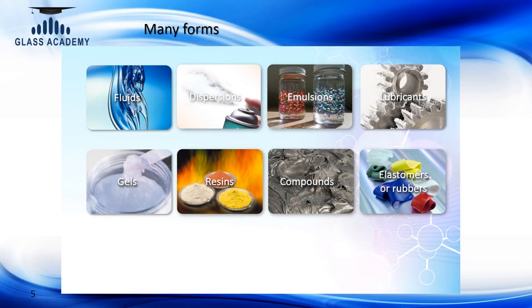So this final polymer which comes out can be converted into different forms. Okay, this can be formed like a fluid, this can act like a dispersion, like an aerosol, or it could be an emulsion with a water based system, or it can also be made into a grease type of compound like a lubricant, and by doing cross-linking polymerization you can make it into a gel, or you can convert it into a resin, compound, or elastomers or rubber. So the essential form of the sealants which are being used for construction applications comes from the elastomers or rubber part of it. So we are going to go into the details of this particular chemistry.